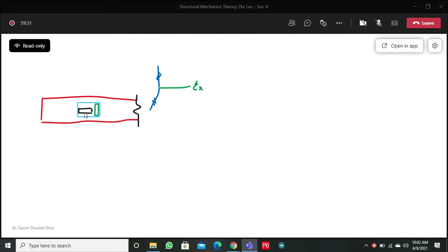Similarly, now you see here this strain gauge will only measure the strain in the y direction. ठीक है जी? Epsilon y. It will not measure the strain in the other 2 directions. So a strain gauge will only measure the strain in the direction in which it is attached. It will not measure the strain in other directions. This is the general concept of the strain gauge: it only measures the normal strain in the direction in which it is attached.